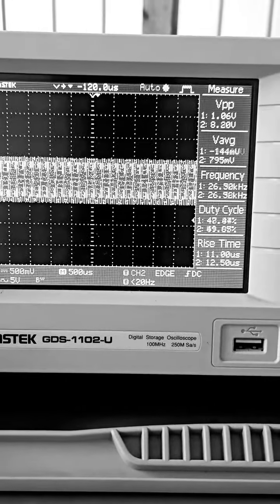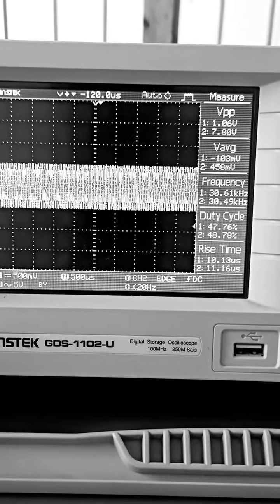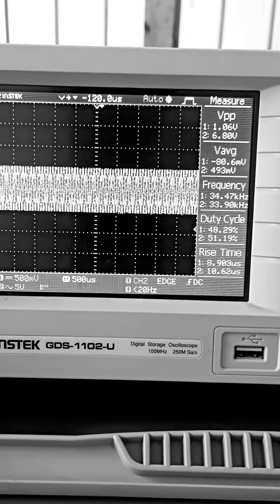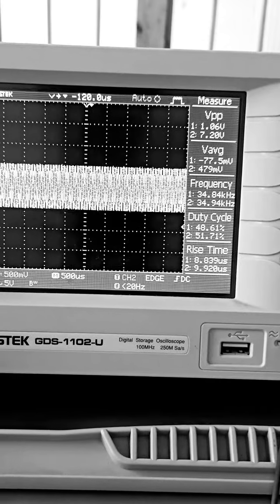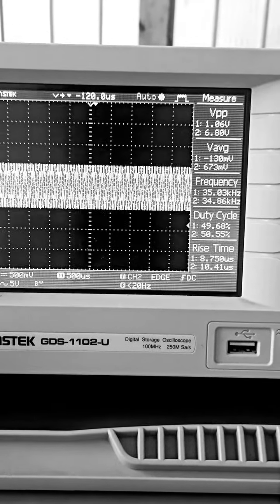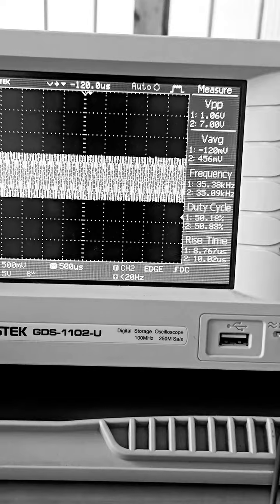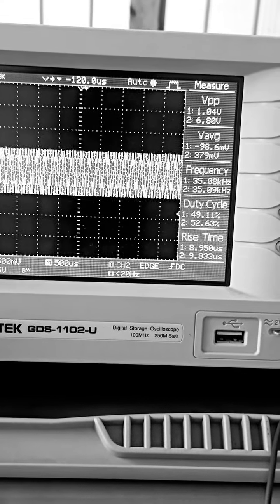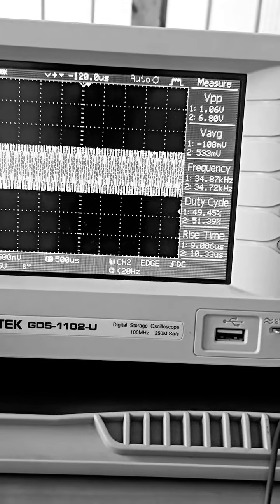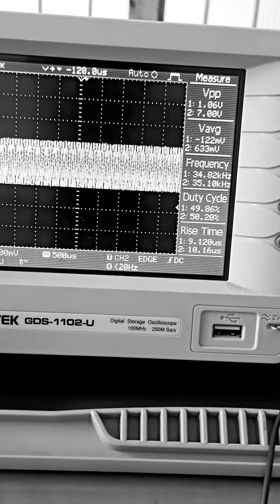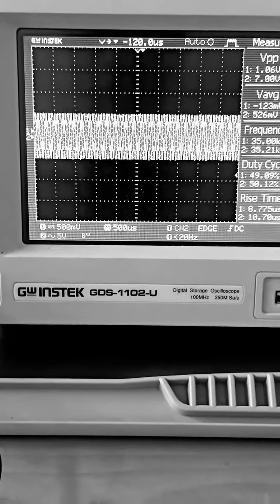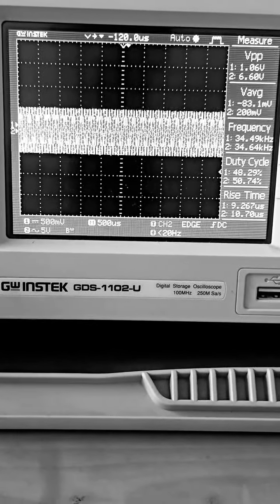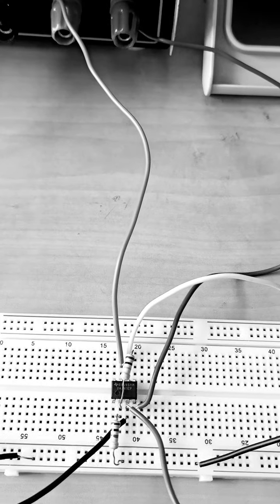Okay. Similarly, with increment in the frequency, the output voltage goes on reducing. So you need to note down the frequency and the output voltage, and the input voltage is fixed, that is 1.12. You have to calculate Vout by Vin, that is the gain, convert that gain into decibels, and then you can plot the frequency response on the semi-log paper.